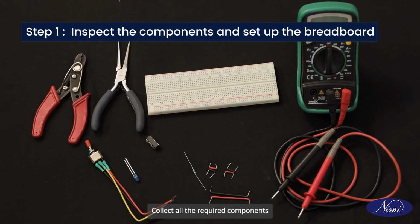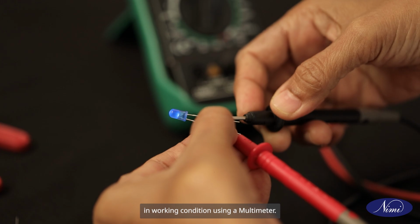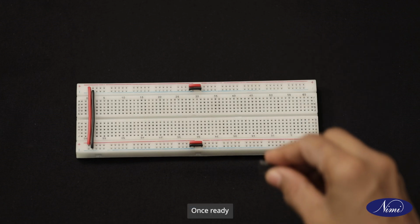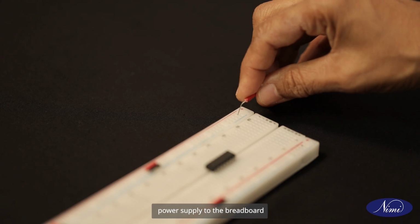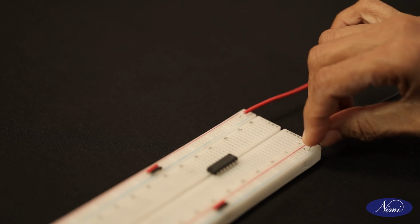Collect all the required components. Ensure the resistor and LED are in a working condition using a multimeter. Once ready, mount the 14-pin IC firmly on the breadboard. Connect linking wires from the power supply to the breadboard.